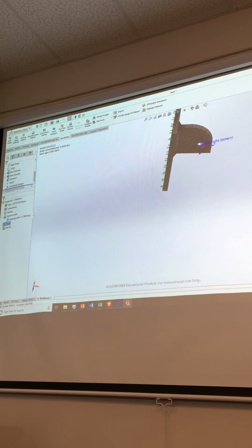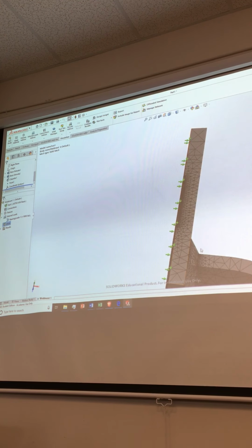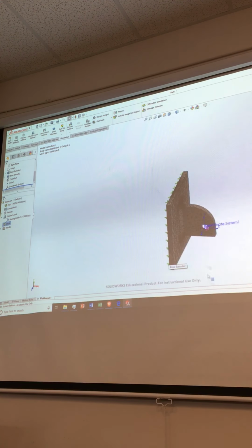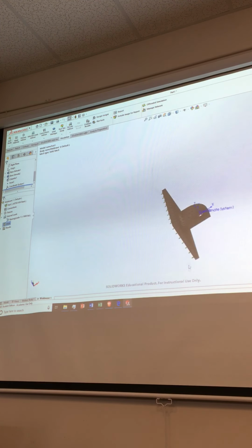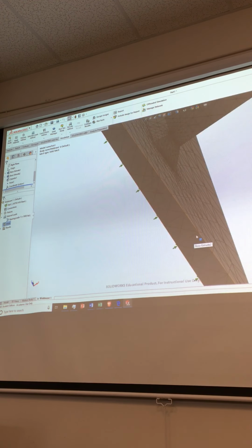See, we have the mesh is very refined up here at the top, right? Now, one of the things that may be an indication is that we're not far enough away, right? It's coming in right in here, so it's making a load path down there, so maybe we need to go up bigger, further away from it, right, because it hasn't gotten its way all out. I don't know if it's doing the same at the bottom though, and it doesn't look like it's doing the same at the bottom, so I don't think I'm getting that.